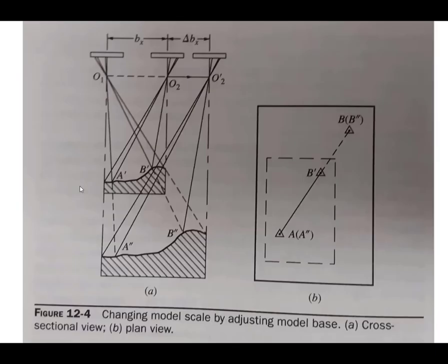Let's review some of the basics of photogrammetry here. It will allow us to experiment with simplifying some of the procedures for determining, or possibly determining, the volumes of the gravel stockpiles. So if you recall, if you have a pair of overlapping images and you want to create a 3D model from the overlapping imagery, we have to complete the interior orientation, which relates the image coordinates to the lens, and then we have to remove lens distortions.